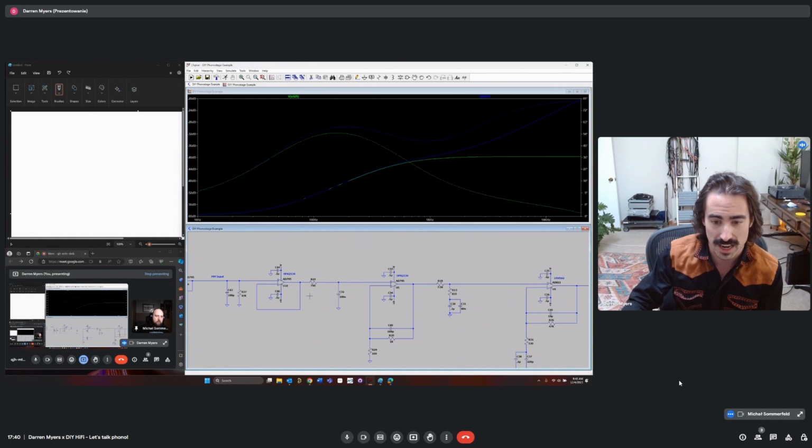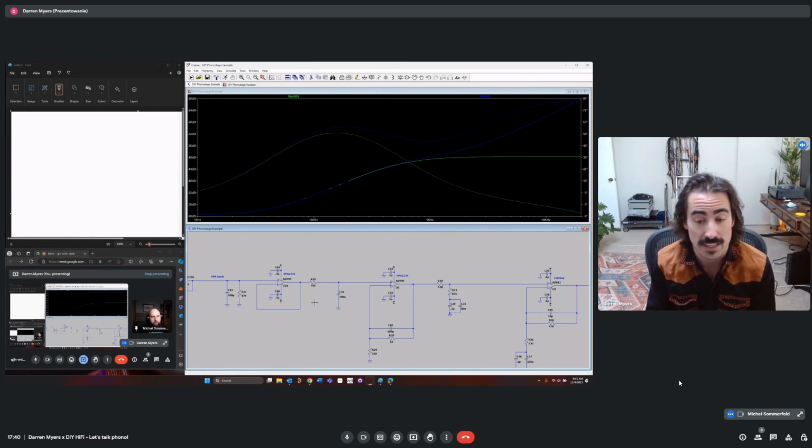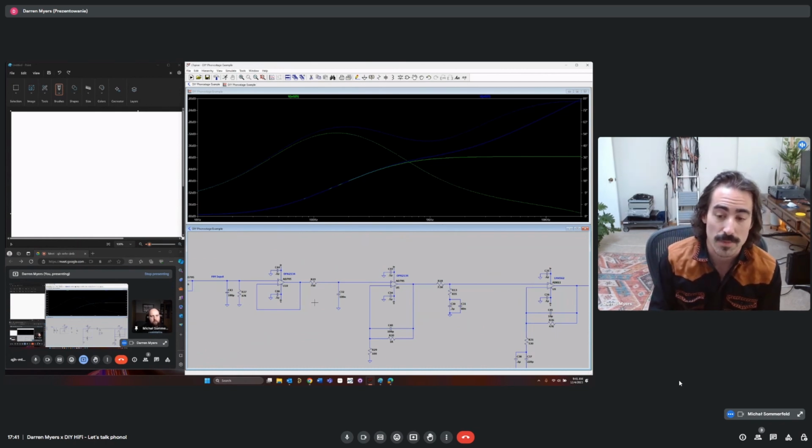Again, the important element to this is that R19 is low in value. At 750 ohms, it still may be dominant in the noise just a tad bit. It's acceptable, but this is still right on the edge. And I use that because we want to stick to a standardized value on our cap, and we also don't want to get too high on the capacitor.